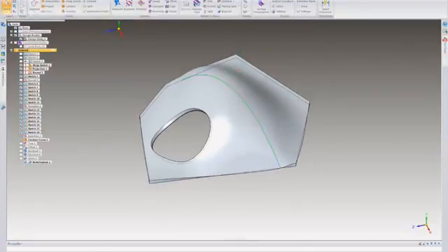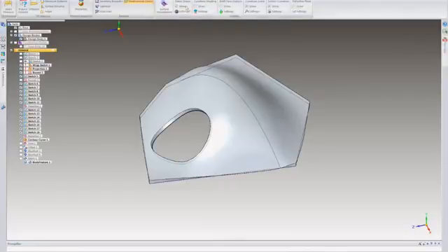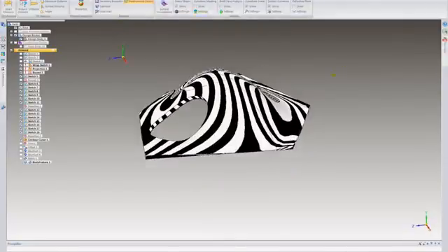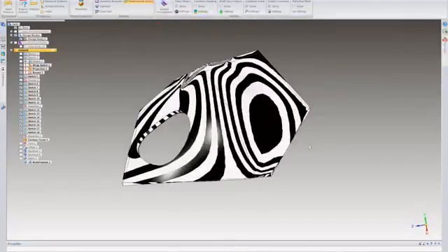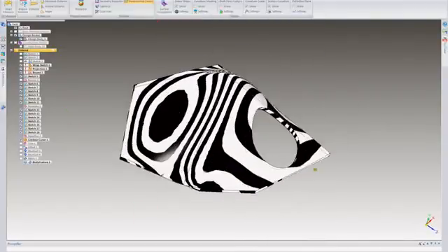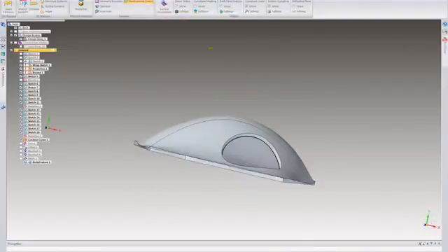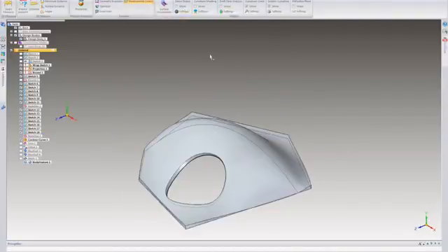All right, so after you're all done, if you ever wanted to inspect your geometry to show the curvatures, to see how tight and how close, as you can see on this side, surfaces wrap across there fairly nicely. So we get nice continuity between the profiles using Bluesurf. It gives you the G2 style of continuity for your surfaces.